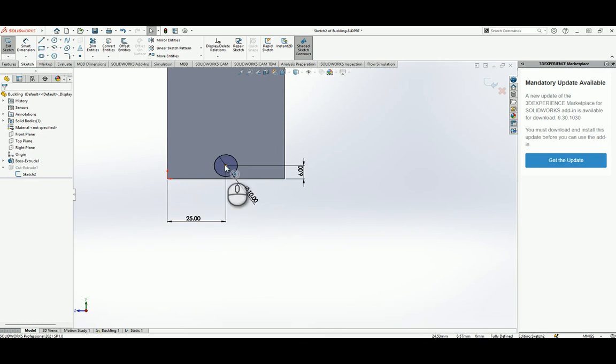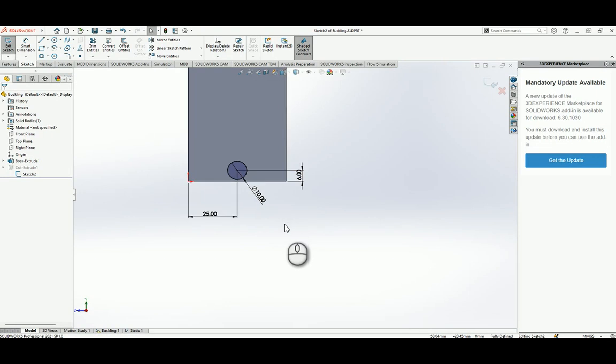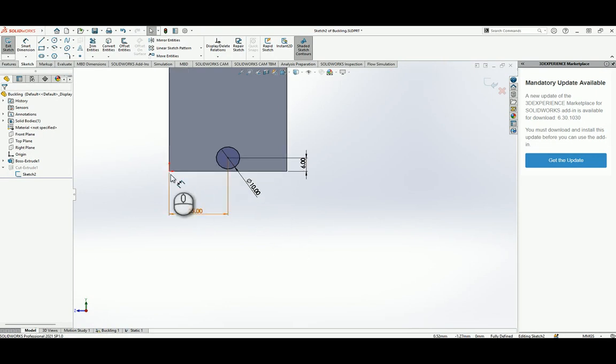So when we actually put the hinge here now, what we are saying is that analytically, our 2.2 meters will actually be less than that because now we are off by 6 millimeters. Right, so it's a small change, but hopefully it will not affect the overall answer as much. Right, to correct this, what we could do, we could actually extend this by 6 millimeters and bring down the hole so that from the center to the top is 2.2 meters.